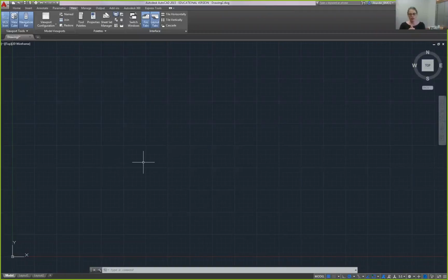And you would have to manually, before you drew any lines, figure out what length line you were going to draw in order to represent that real world dimension. In AutoCAD, we always draw to the real world physical dimensions. And then we don't worry about scale factor until we get ready to plot it.